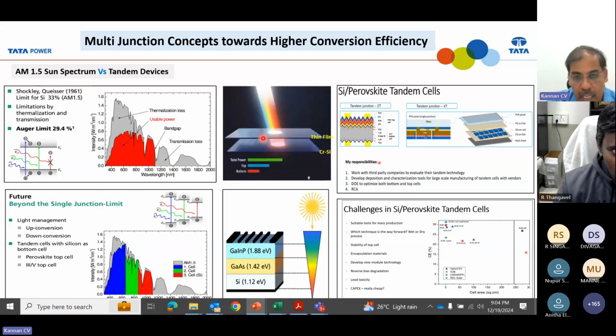1.7 eV band gap, then automatically the higher band gap material works for the UV. It will effectively convert the UV light into electricity. So by doing multiple junctions instead of a single junction, you can add a higher band gap material on top: one PN junction, another material with another PN junction with a different band gap, so that the top one will capture the entire UV spectrum, and whatever is left out, it will not capture; the bottom will.